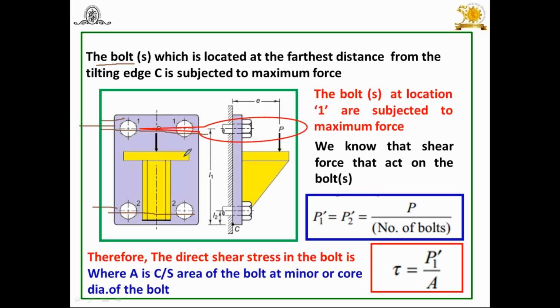Patil, you will find in direct secondary shear stress case, it's a resisting force again, resisting shear force. Earlier case, I am talking about the case explained by Professor V.K. Patil, secondary shear forces. During that time, you will find R1, R2, R3 they are the distances of the bolt position from the CG. And which bolt position is farthest position from the CG, where you will get the maximum